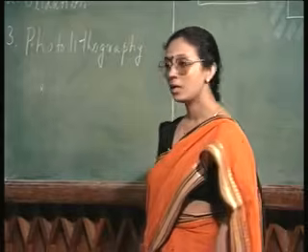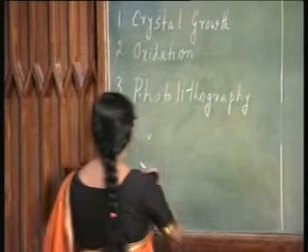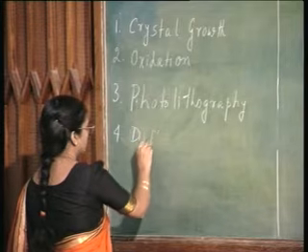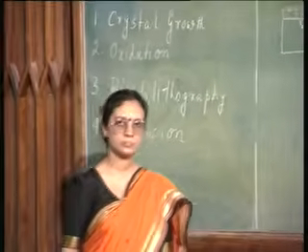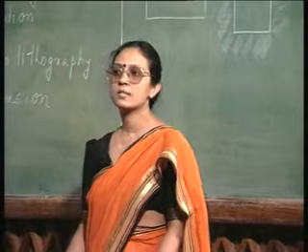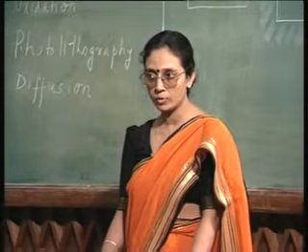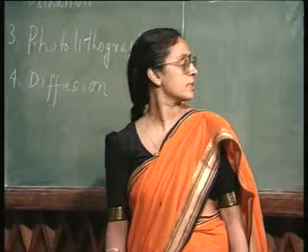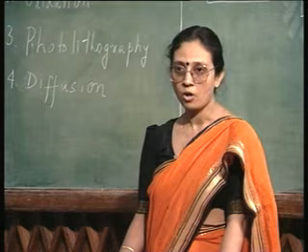So, that is our fourth process step, that of diffusion. This particular diffusion incidentally is called buried layer diffusion. Why it is called buried layer diffusion will become clear in a few minutes. This N plus layer diffusion, usually the dopant used for this is antimony or arsenic.